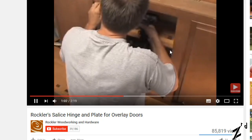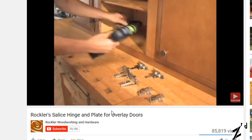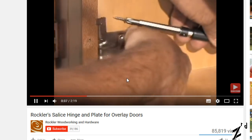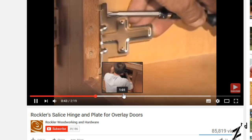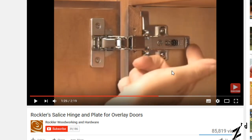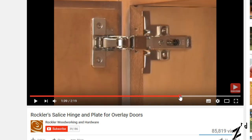Okay, so this works. This is what Kiran's found. These are the different parts of the particular hinge and how you fix it, which you can obviously watch in the video yourself. I just want to show this is what it looks like when it's installed. One portion is here, the main portion is here. This part actually goes into the door itself for a slight bit. This part is kind of like a pivot plus a telescopic hinge, which is a slightly weird mechanism.